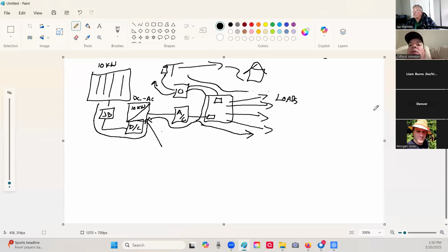I have a question. Sure. So when you're doing Enphase and you have more than one array and you have the little microinverters when you're looking in the box, would each array have its own full inverter then on top by the junction box? Or would they still only have one? Yeah, if you've got microinverters, then there's no need for another inverter.